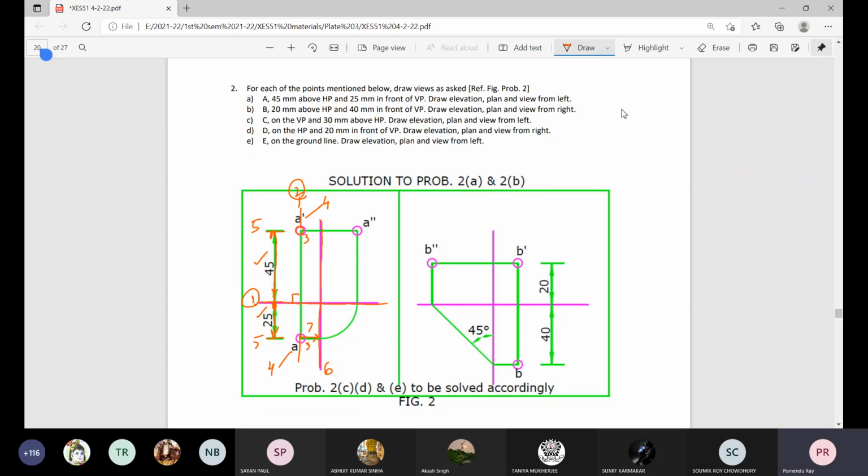Next step, about this center, taking this distance as radius, draw this quarter circular arc to reach up to this point. That is step 8. Step 9 is draw a vertical line through this point. Maybe it will extend a little bit.